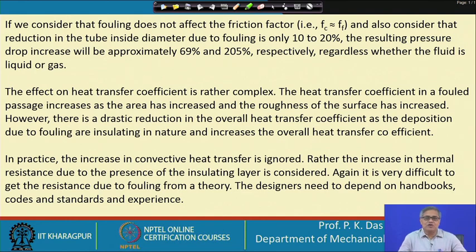There is another aspect also: what should be the cleaning schedule, up to how much time we can allow the foulant to deposit on the surface, so that the deterioration of the heat transfer performance is within the level of my expectation, and then I have to definitely clean the heat exchanger, so that it again performs in a better way.